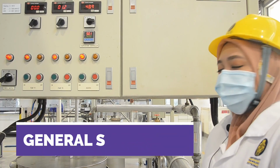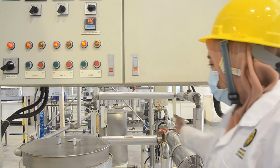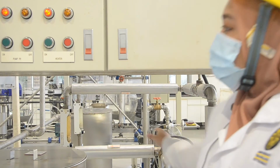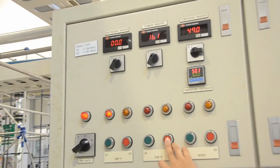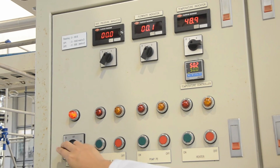Okay, now I will explain the general shutdown procedure for this equipment. Please make sure that all the valves are closed. Then you can start to switch off the heater, pump 2, pump 1, and then also switch off the equipment.